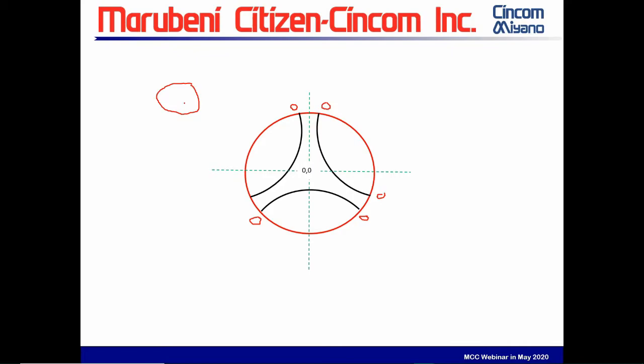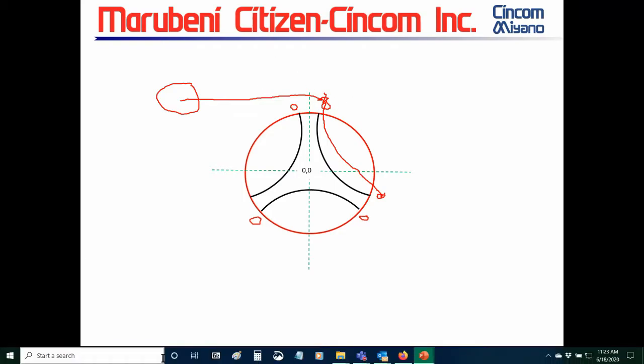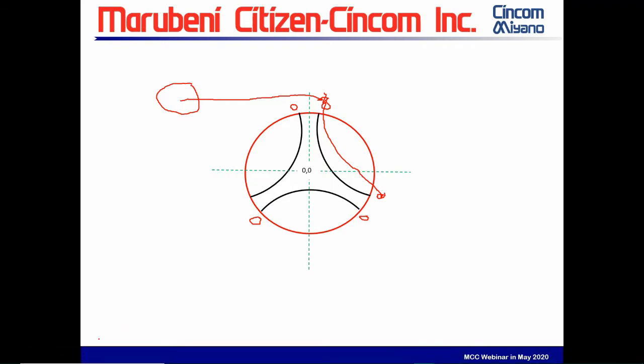And I'm sorry, it's not going to be very round. You move the cutter to this transition point over here. Then you program it just to do the radius going to this transition point here. So you would have the number for this part here. That's a little dot you can't see. It's not what I wanted.